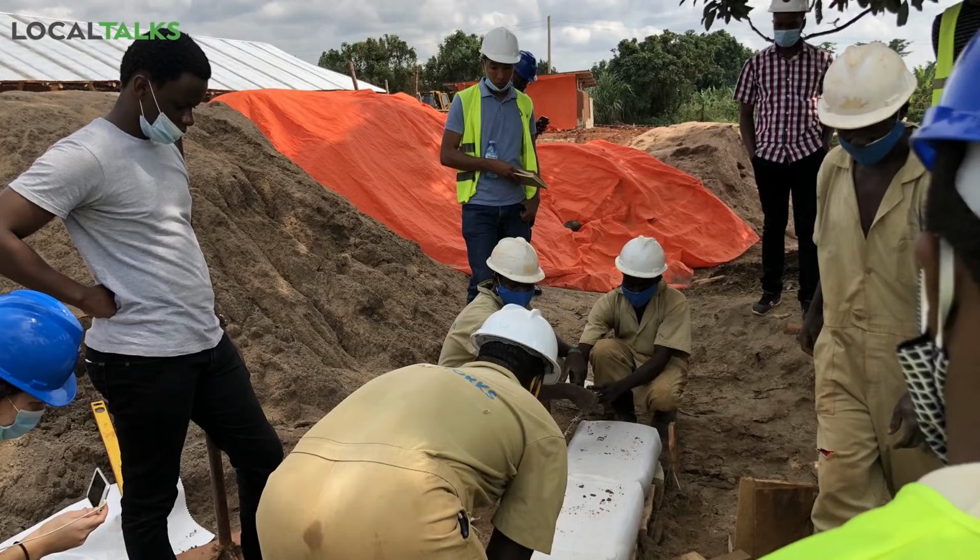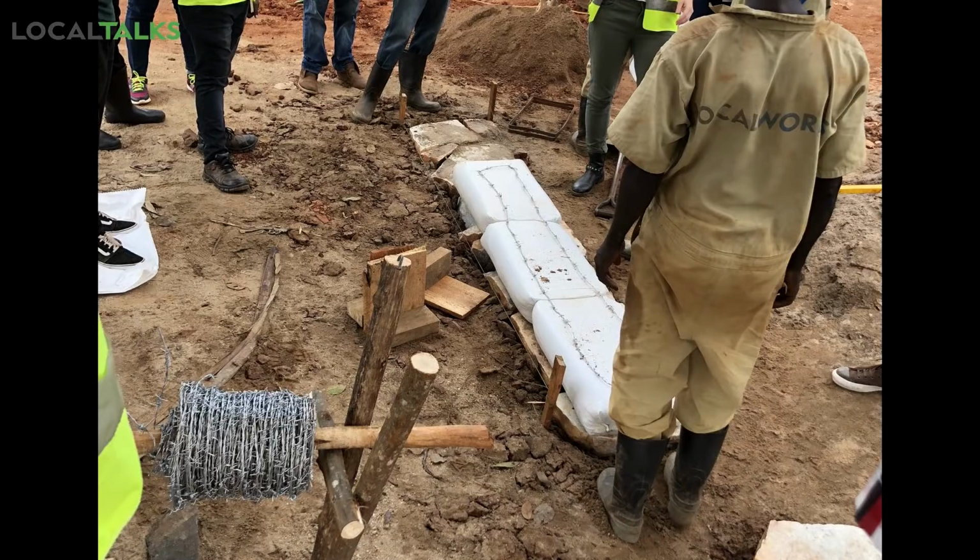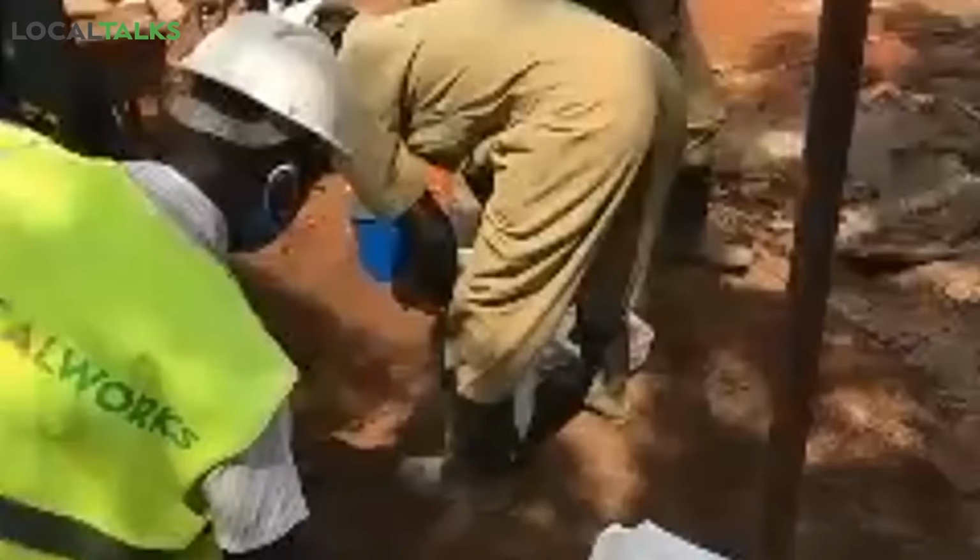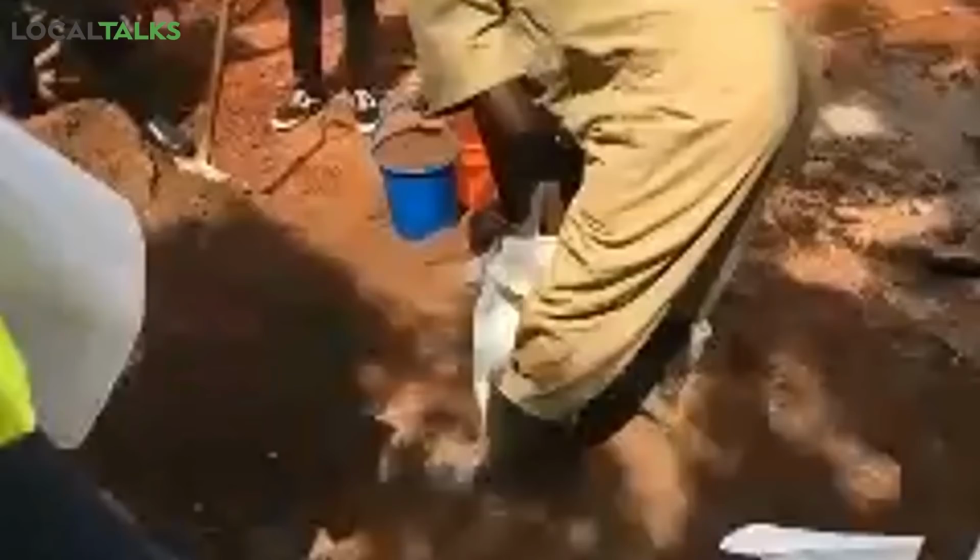So the guys are now filling these buckets and pouring them into the bag. How many go into one bag? Four. In fact, they also help if you want to maintain uniformity of that height. That first bucket is already in the bag. So it is not just a matter of pouring it into the bucket, it is also about pre-compacting the material into the bag. Now comes the second bucket.